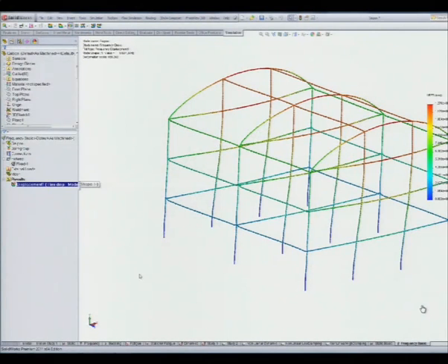In this case it is more complex, because you have to include equipment, other forces. What I usually do, if I have the walls, is use a remote mass. For example, this is another way. So you use a remote mass in order to take that into account, that's very important.